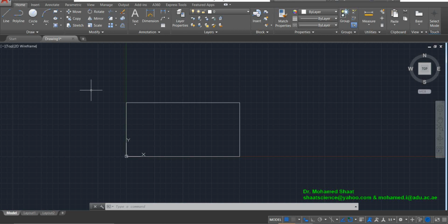Whatever this space is, two-dimensional space like XY coordinates, or three-dimensional space if we are working in 3D modeling, right? So basically, AutoCAD works with these concepts. For example, if you give a command to AutoCAD to move the object with all of its coordinates from one location to another, AutoCAD asks us to provide some information about the start base point and the other point.